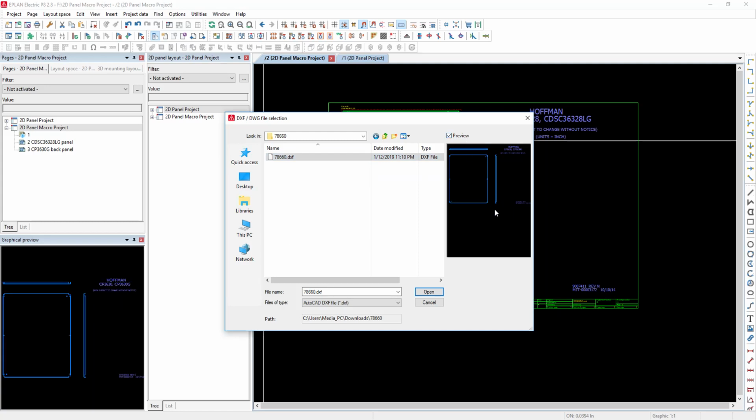One of the disclaimers I highly recommend is that when you're importing or downloading files such as DXF files, ideally the file should be clean. ePlan is not a native DXF file generator, if you will. Sometimes if the lines haven't been broken or things haven't been done properly, like explode or other functions you need to do to clean up the DXF, you'll notice that with the preview on, it won't show up. So there's something wrong with that file.